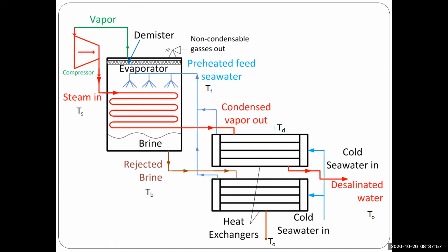in. So in this unit, we do not have a condenser because we do not need a condenser, but rather we have a couple of heat exchangers which are utilized so that we can make use of the energy associated with the rejected stream, rejected brine at high temperature, rejected distillate at relatively high temperature. Both of these energies are being made use of to preheat the feed. And accordingly, instead of throwing these streams at high temperature to the surroundings, we are using them for preheating the feed. So this is the basic idea that we have for this unit.